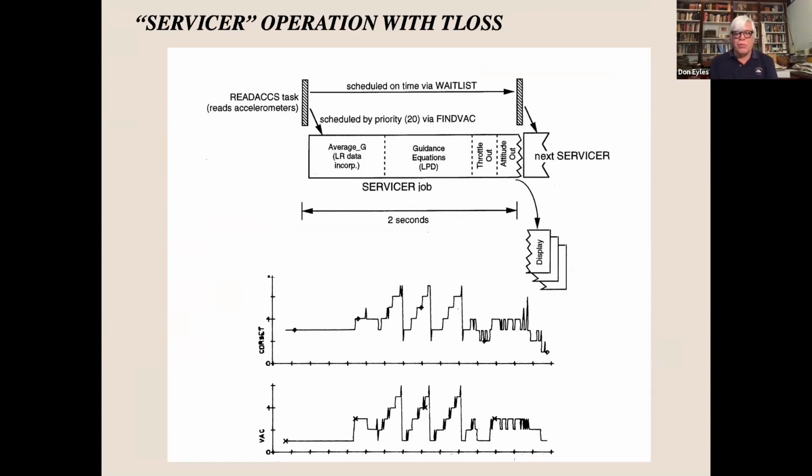The first 2 were in P63 when we had a margin of something like 14 or 15%, which should have accommodated the load that the glitch was putting on us. But at one point, Buzz Aldrin did want to see the radar correcting the state vector. So he used verb 16 to select a different noun. I believe it was noun 68. That created that job we looked at earlier called Mondo. That pushed our margin below 13%. Therefore, we had an alarm.